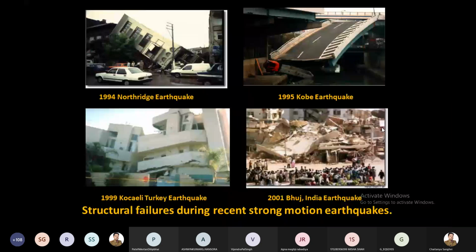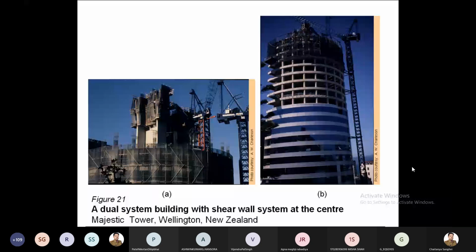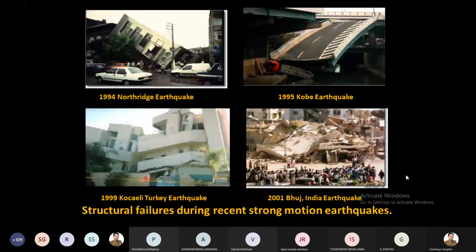While in earthquake resistant design, you are not actually designing for the full level of the earthquake force, right? So we have seen that we are designing for 20% or 30% force, right? This is the most important part, I tell you. Actual load coming on your column is 100 kilonewton, a lateral force. You are designing for 20%, 30% force, and still you are saying my structure is safe, right?